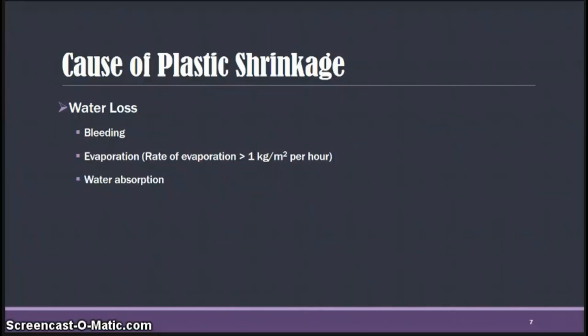That is, the non-exposed surface of the concrete will be subjected to shrinkage here. Another important cause of plastic shrinkage is bulging or settlement of the formwork. If the formwork is not strong enough, it's going to bulge out and it's going to cause volume changes in the concrete.